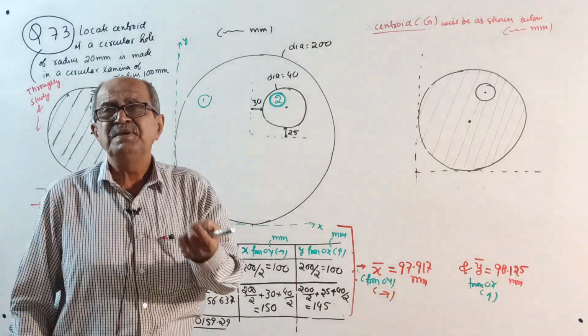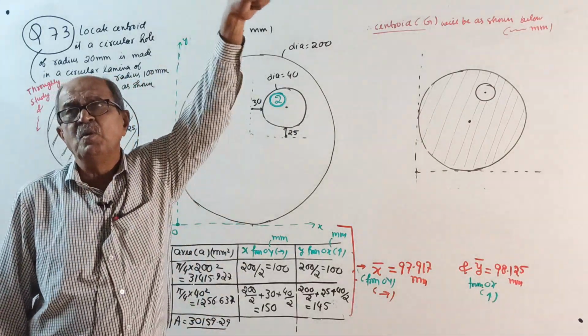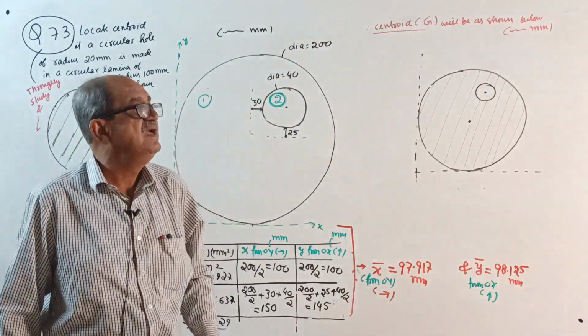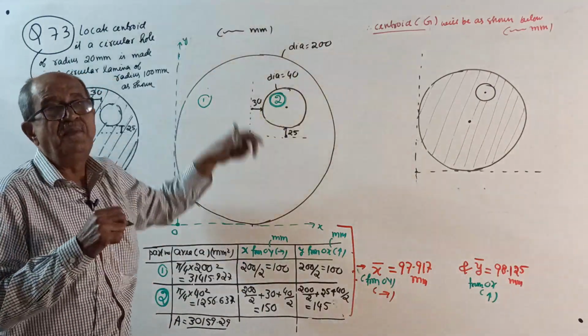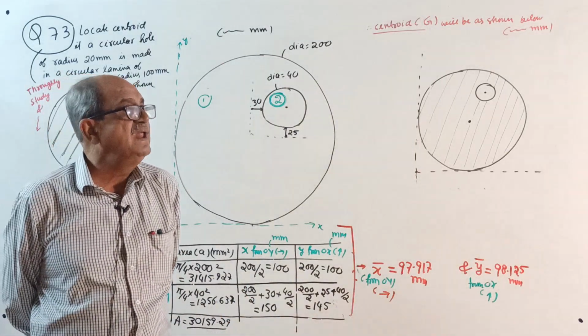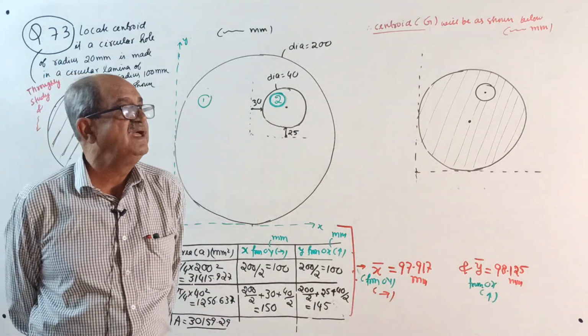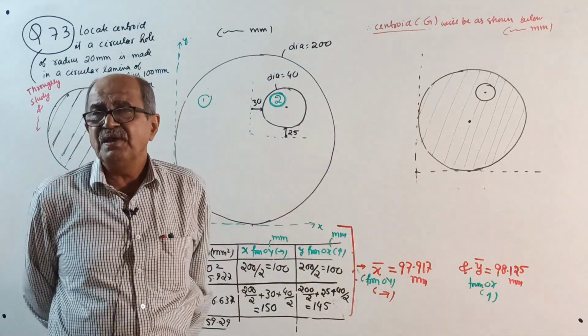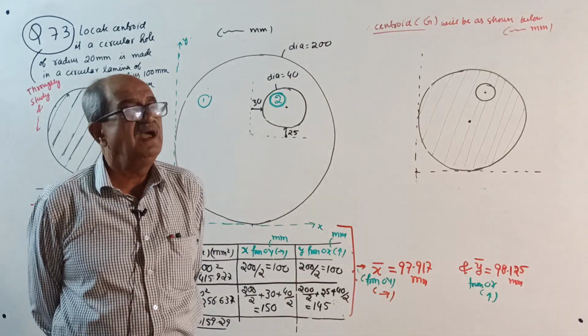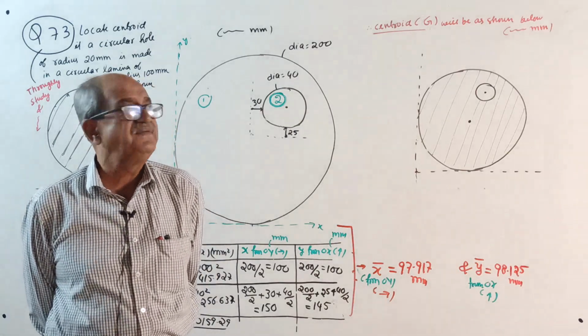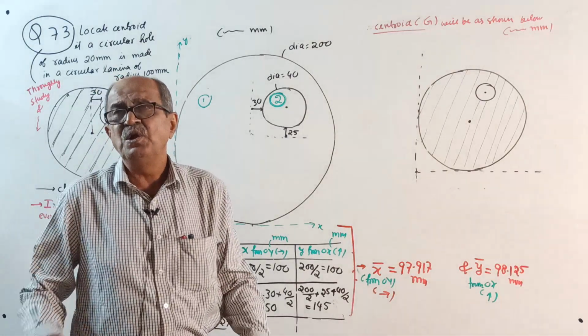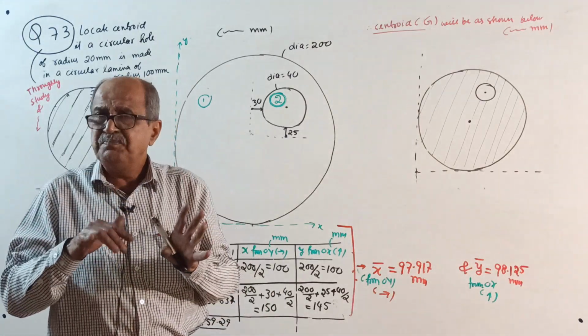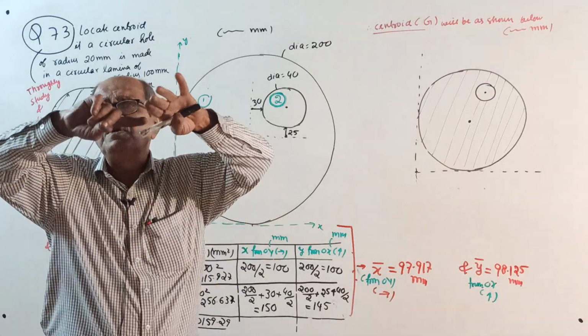Then he asked me, sir, what is the problem? When you go to moment of inertia, be careful. There, your formula will become minus Ig minus A square. Confusion. Full formula will be Ig plus A square, but for the removed area, you are trying to minus Ig minus A square. Or what you will do is, you will put Ig plus A square, entire thing will subtract.